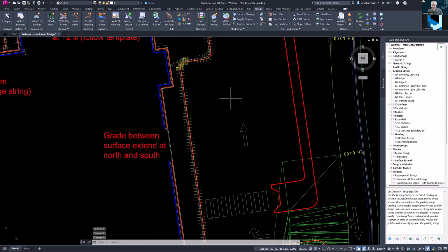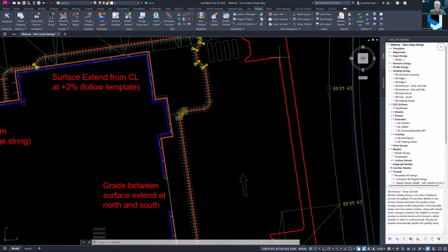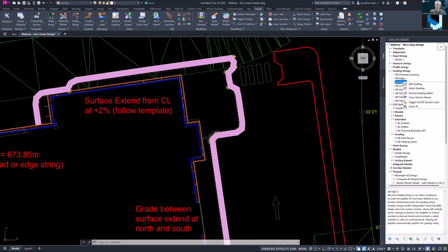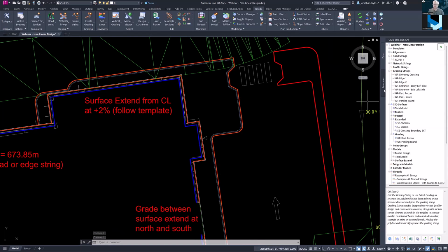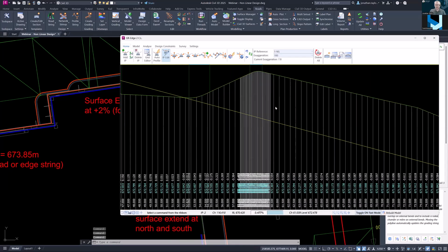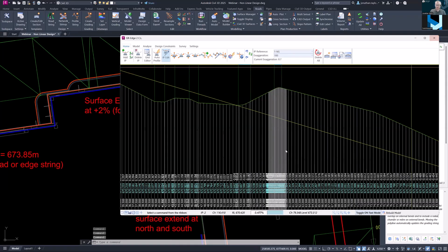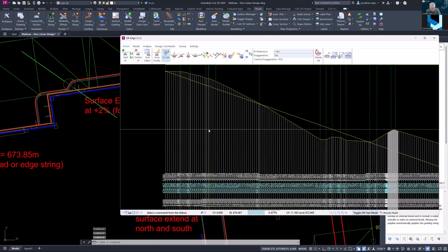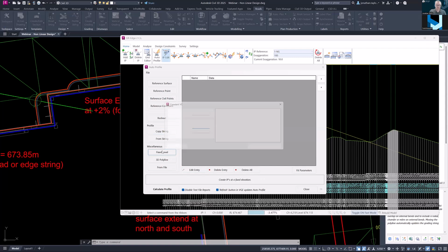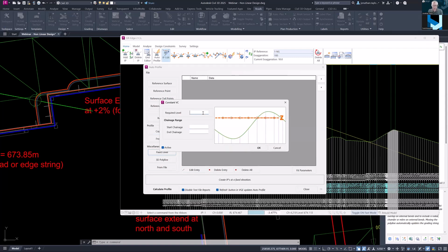So I wanted to mention that because that does occur on other grading strings on here. That radius there is less than a meter, so is that one. You have to introduce extra sections, but it means for your sampling, for your whole string, you can have a large sampling value. Let's just turn off the sample lines for that, and let's just get back to what I was showing you before, which is to introduce the levels. So, oh, that's right, yeah, because I was going to. So yes, they will appear, by the way. You can't do anything about displaying those unless I had that box checked. I can't remember.